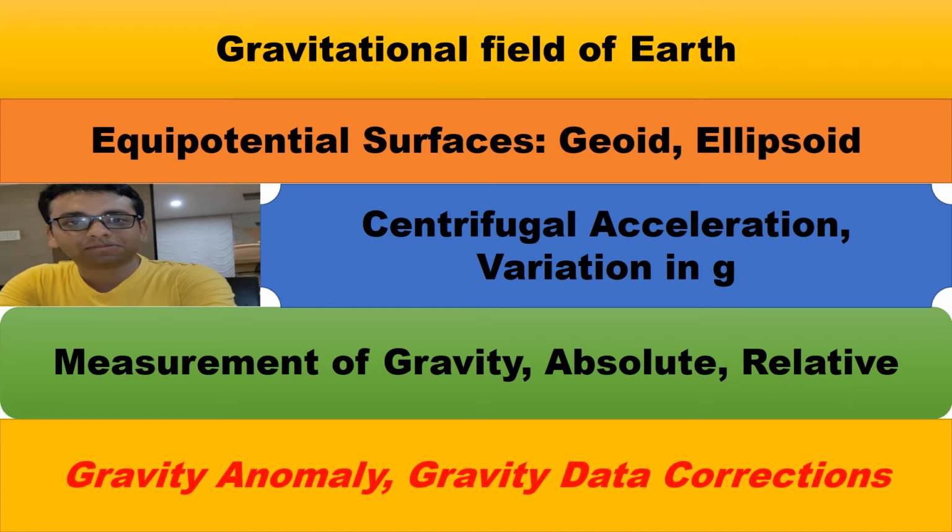Hello everyone. In this lecture, I'll discuss with you first the gravitational field of the Earth, the equipotential surfaces, that means the geoid and the ellipsoid, how to measure gravity, absolute and relative, and the gravity anomaly. I will describe the gravity anomalies in detail and how we measure gravity data in real practical applications. What are the corrections?